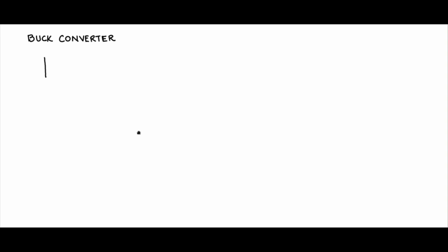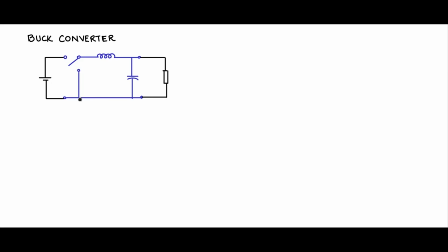Let us now try to understand the buck converter. There is this unregulated voltage source Vi here, and this is the single pole double throw switch, an inductor followed by capacitance. Now these blue portions are the inside components of the buck converter. The black portion are external, not under your control for design, and this is the load. So let us complete. Now this is the buck converter circuit we have seen and discussed.